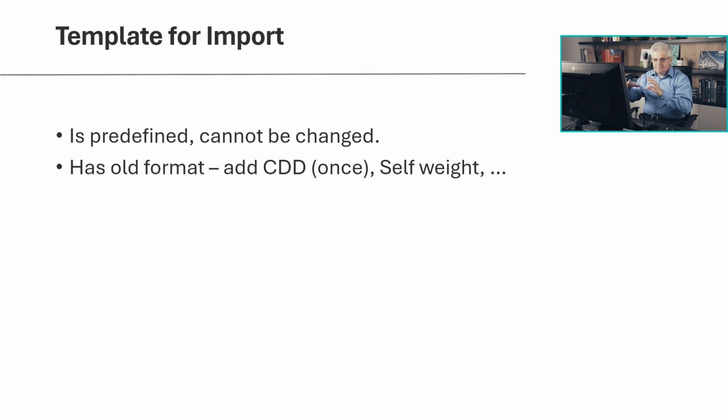But what you can do is later, after the import, you can insert your model from IFC file to your template, or on the opposite way, you can insert your template into the model, whatever you want, both will function.